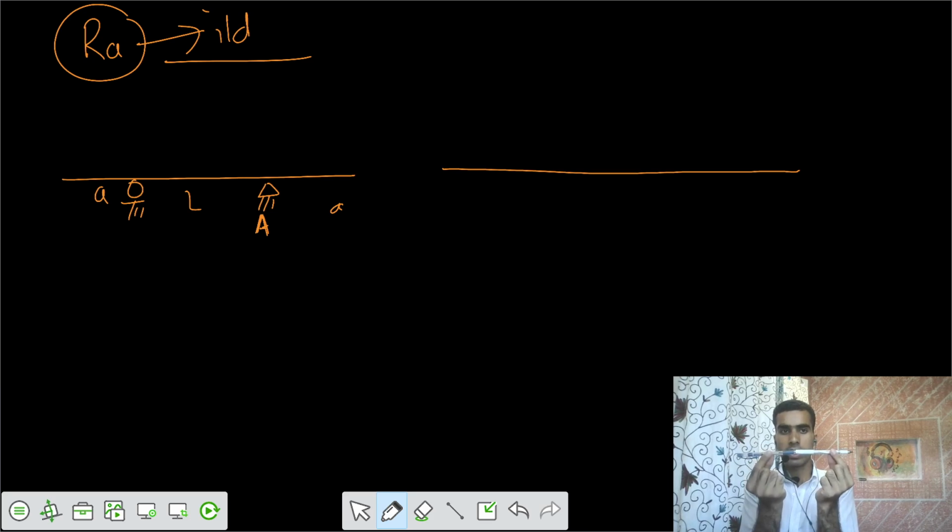Now we need to do one thing. To get the reaction at A, you remove the support at A. You remove the restraint offered by A. Now you apply a unit displacement at point A, because the reaction is upwards. In the direction of reaction, you have to apply one unit of displacement upwards. Once you apply 1 unit displacement, the profile would be in this fashion.